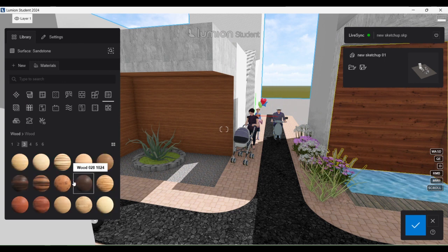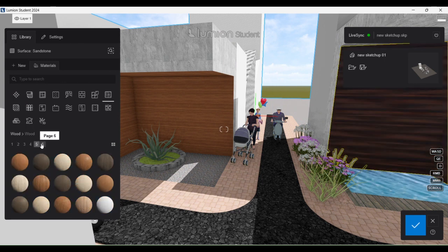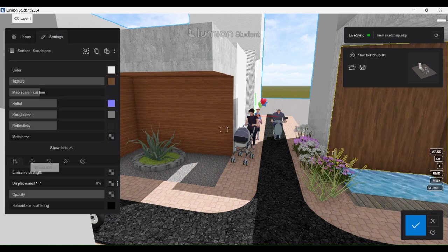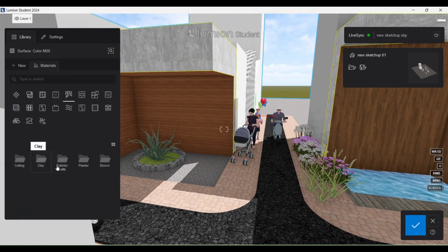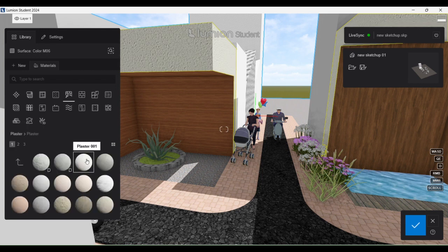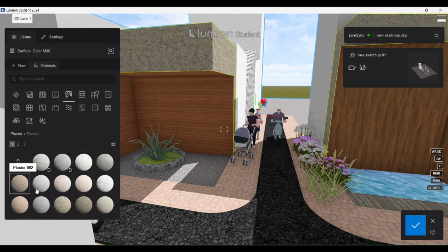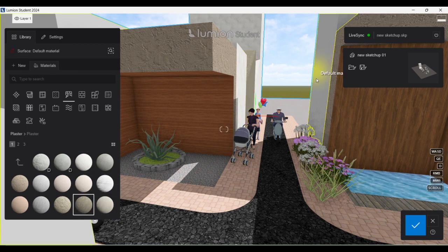For context, you will keep something gray. In the plasters, something in gray for external walls. Yeah, this would be better to keep everything in a warm tone. And then you color or give material to all the context blocks that we've done. And if you see that the reflection of that building is too much, here you can reduce the reflectiveness. That's why you reduce the reflectivity of all the surfaces that you give.